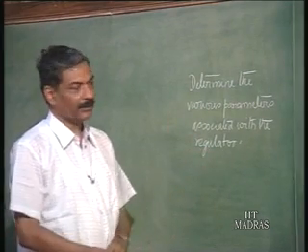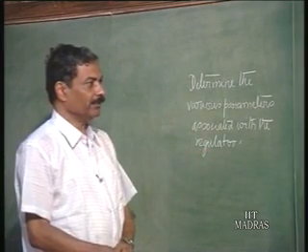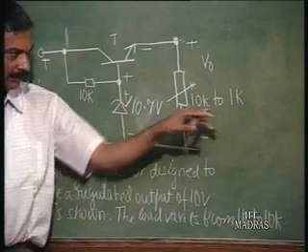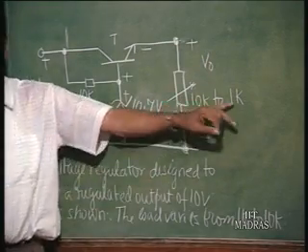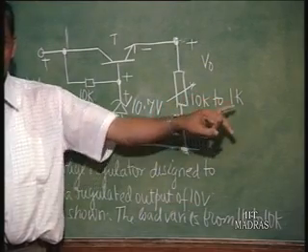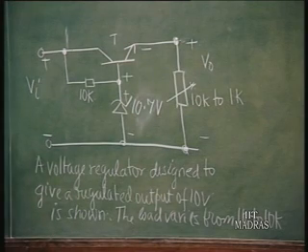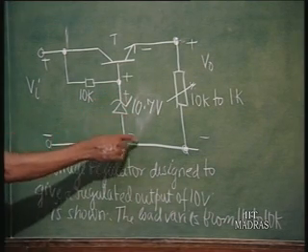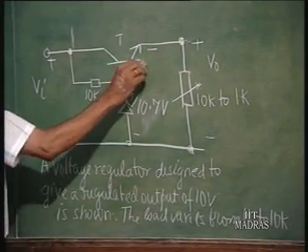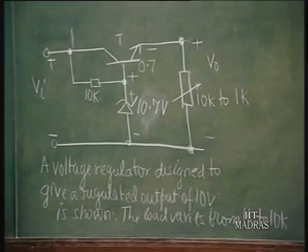Let us try to understand this regulator, which has been made to work for a load variation of 1 k to 10 k. I put it as 10 k to 1 k because it gets more loaded as the resistance decreases. So, as you can see, zener voltage is 10.7, there is a drop of about 0.7 here.